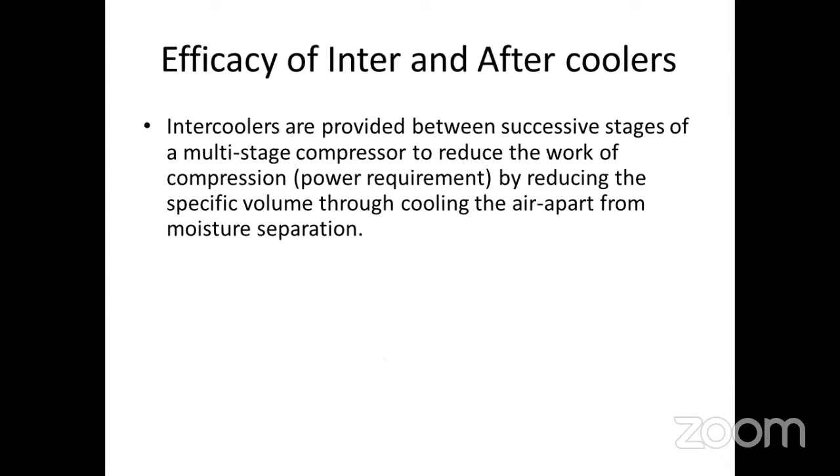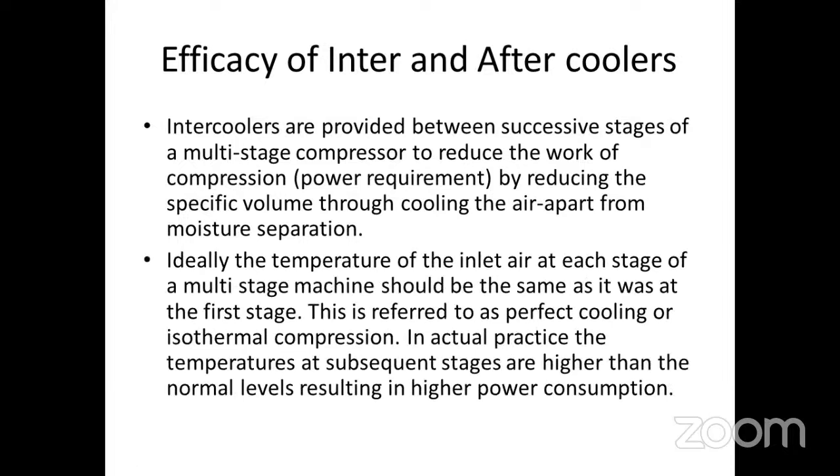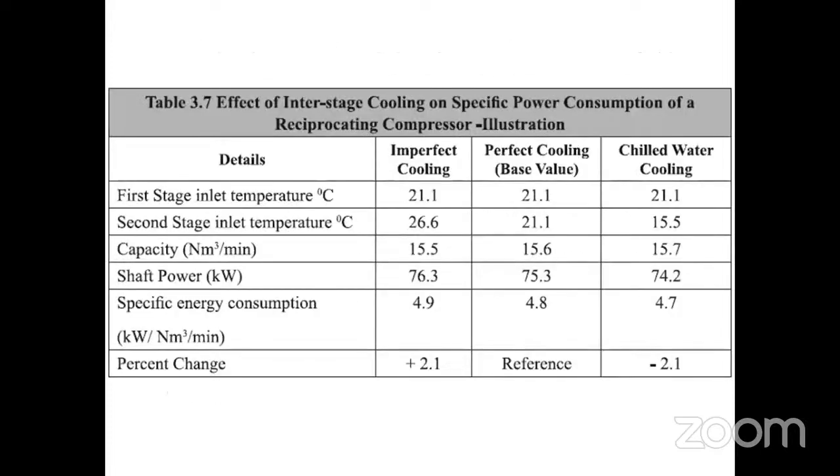Intercoolers are provided for each stage of a multi-stage compressor to reduce the work of compression. Please keep this in mind, sir. Intercoolers are used to reduce the compression power requirement by reducing the specific volume through cooling the air, apart from moisture separation. We have already seen it. Effect of interstage cooling on specific power consumption. We can see it directly, sir.